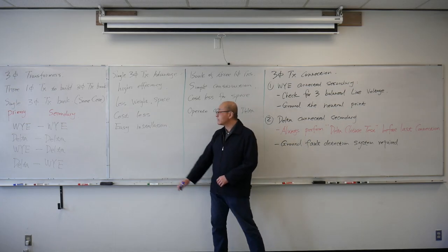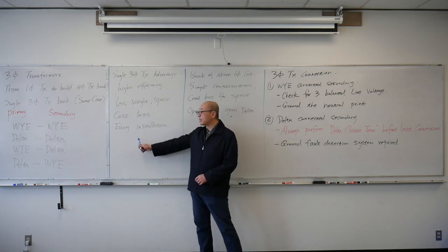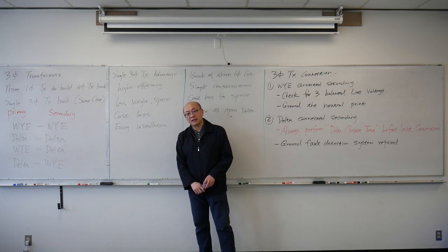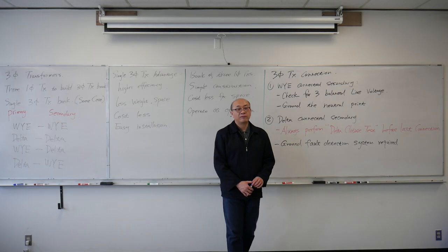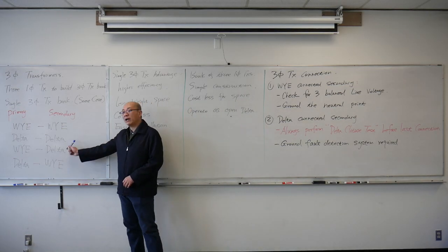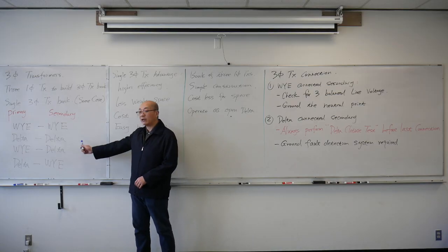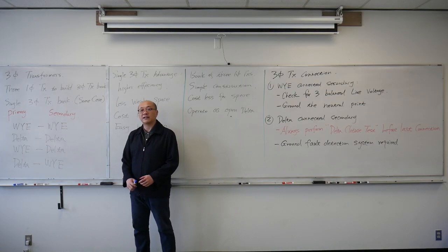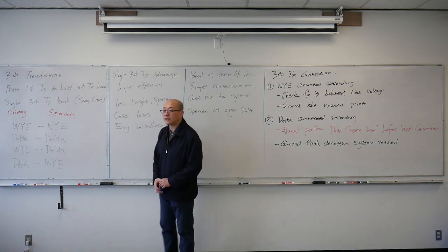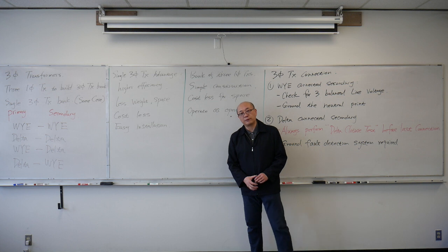The last one is that for a single three-phase transformer bank, it's much easier to install, because usually, if I have a Y-Y transformer, it will have H1, H2, H3, and H0, and X1, X2, X3, and X0. It's much easier to do the connection compared to three single-phase transformers.